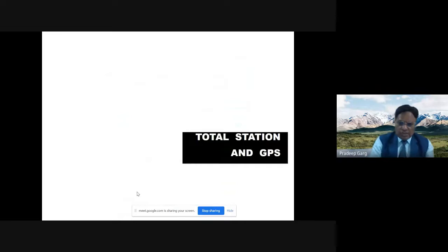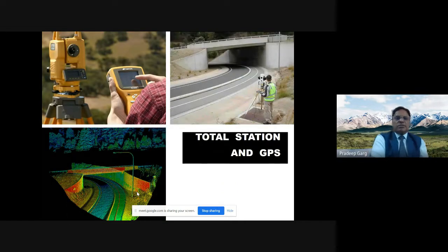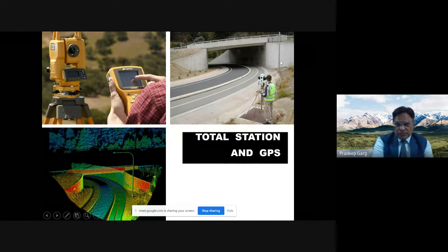to get the location. People are using a combination of electronic total station and the GPS when it comes to 3D modeling. So as you can see, the second image is the ground. The person is standing on the ground collecting the information about this particular bridge. There is an electric pole and there is a road here, and the bottom colored image is the point cloud data, and you can see here that the electric pole has come out very nicely.